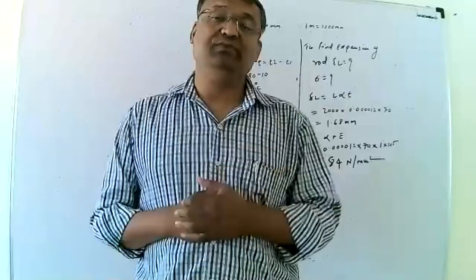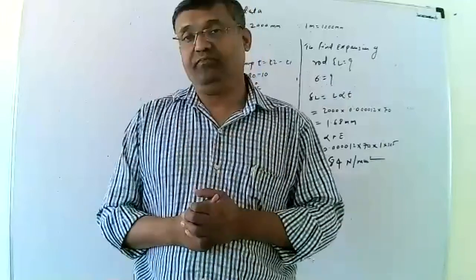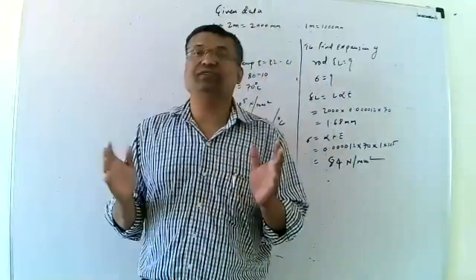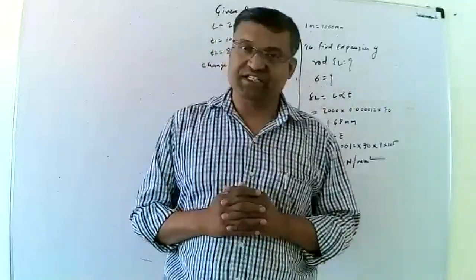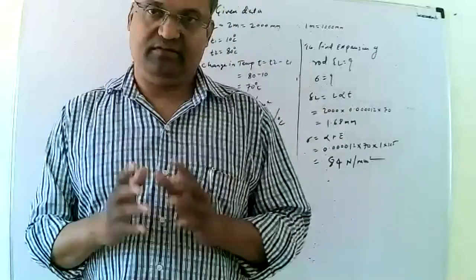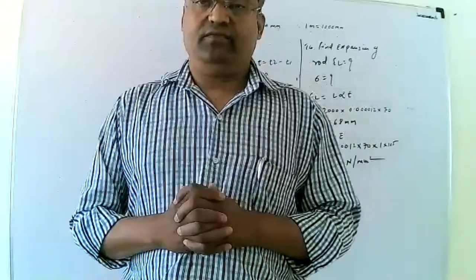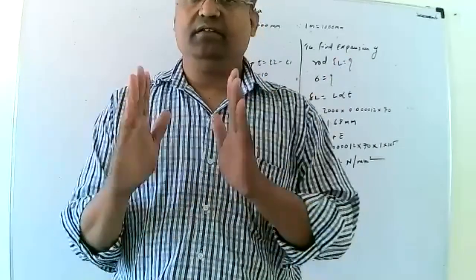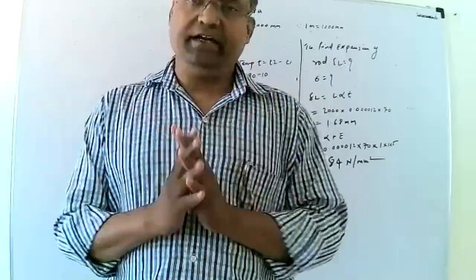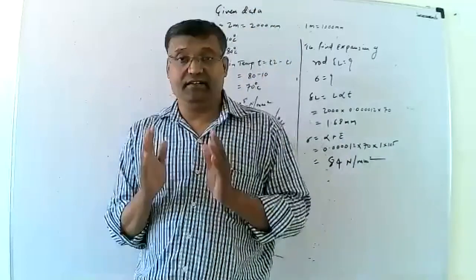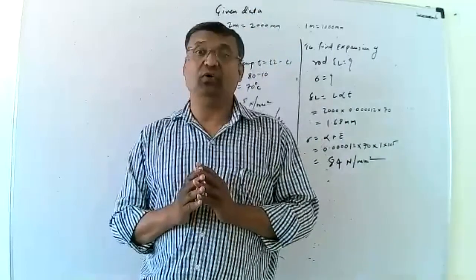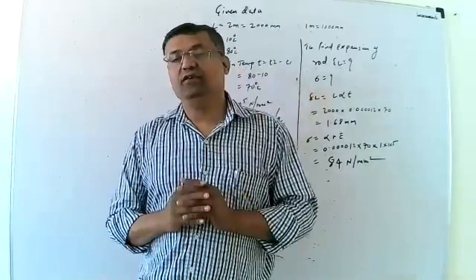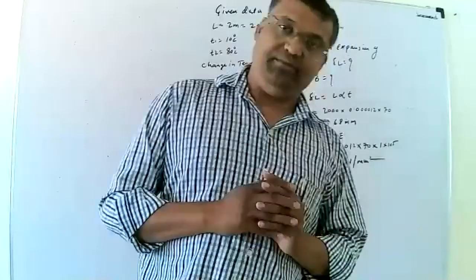We know that stress will be generated in the specimen, and it will be resisted by the two fixed end supports. The supports prevent the expansion of the specimen, and compressive stress will be generated in the specimen.